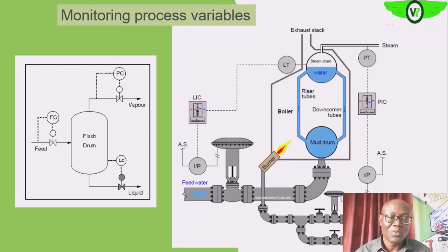They will go into the vapor state and rise up, while those that did not flash out, those that are still liquid, will remain in the liquid form and settle at the base of this drum. So it is a kind of separation process where you separate the lighter component of the mixture from the heavier component of the mixture.